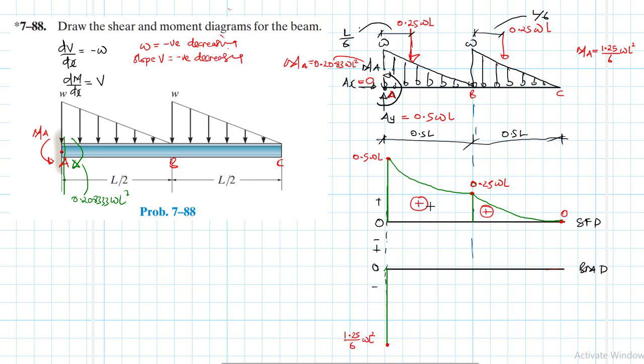This we did already in our shear force diagram. But our shear itself is positive and it is decreasing, right? And the slope, therefore, of the moment that we need now is going to be positive and also decreasing. And this is what we want right now. So we know that the slope is going to be something like this, positive but decreasing, right?